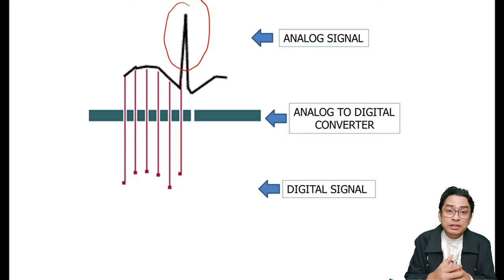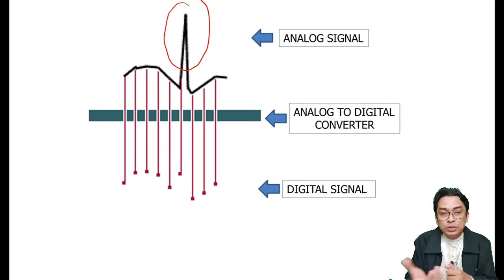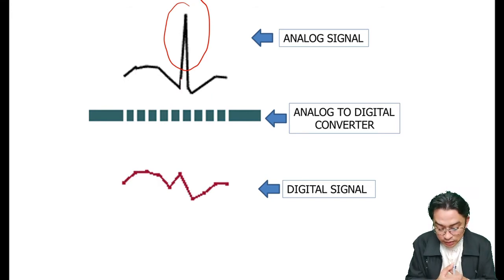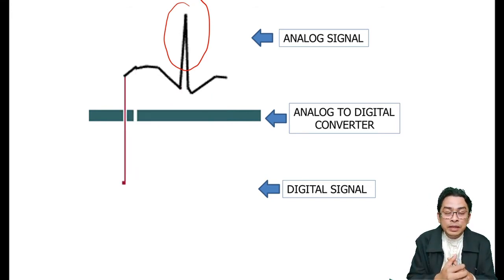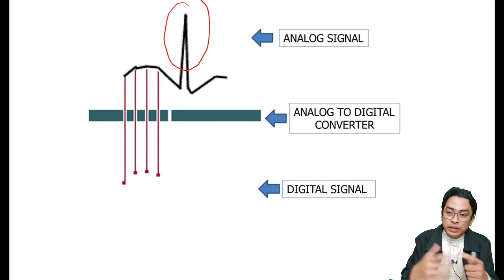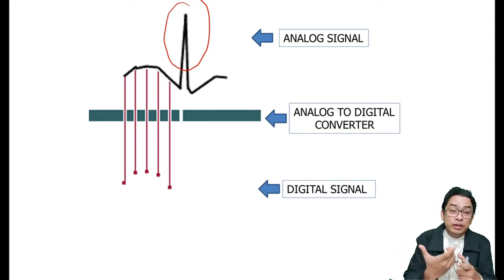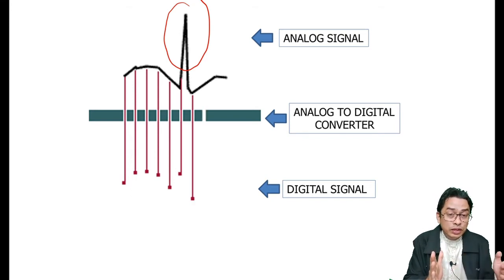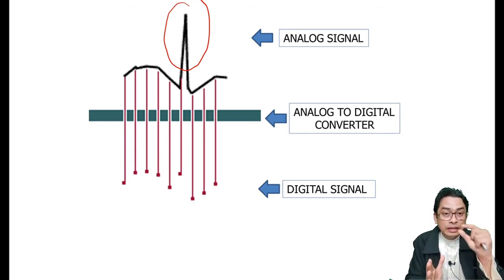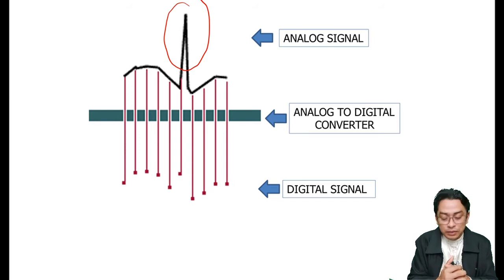We will save the signal after we do processing. That is also one of the things that we can do for instrumentation. That comes to the virtual instrumentation software, whereby we can only view a very fast signal, set a high sampling rate, but for the storage we only store relevant information.